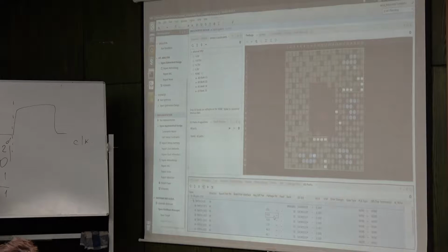This is what we call circuit constraints. This is the physical constraint, and often this constraint defines the location of your sub-circuit within the chip. Normally Vivado tries to put your circuit as close to the pins that you are using as possible. Yeah, that is all for constraints.